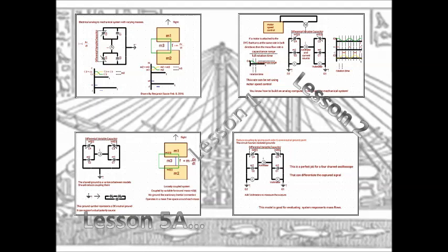In this lesson, I will complete the series by giving a complete example of the modeling and simulation process using analogous circuits. I will use the methods on the same system that I described before, and I hope that by the end of this lesson I will have given you a clear example of how the electrical analog is used for modeling and simulation of the mechanical system. I will use the simulation power of the LTSPICE electrical circuit simulator to help me achieve my objectives.